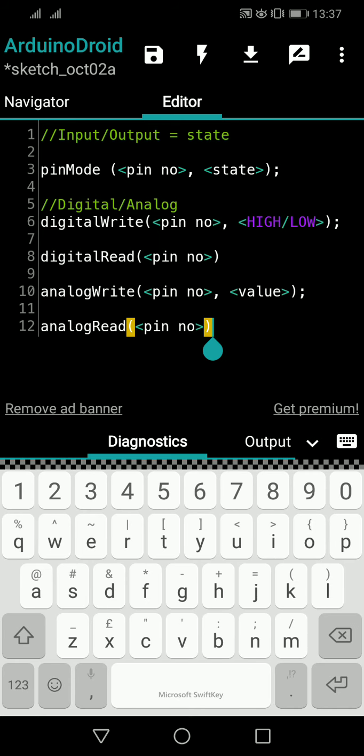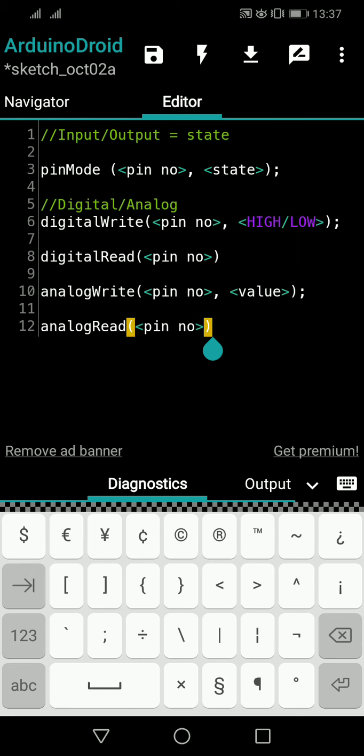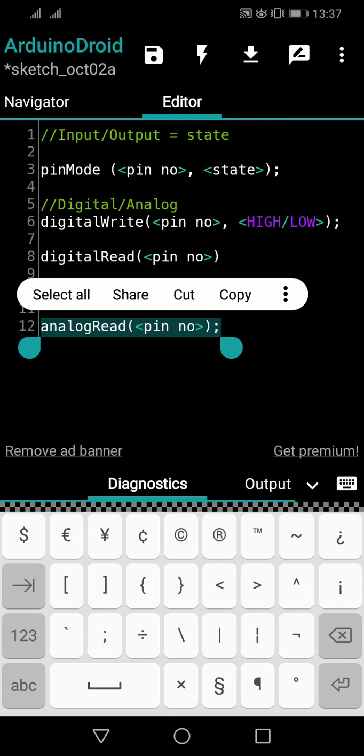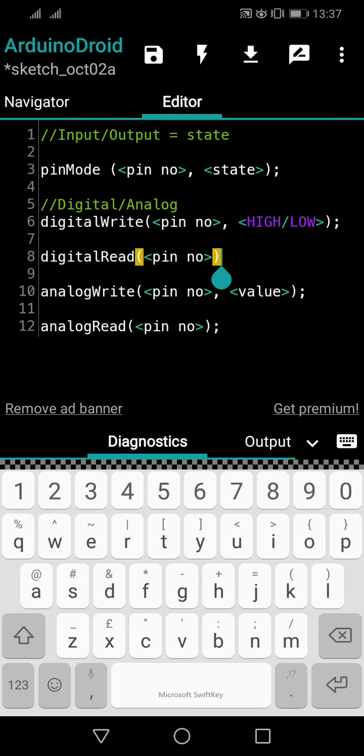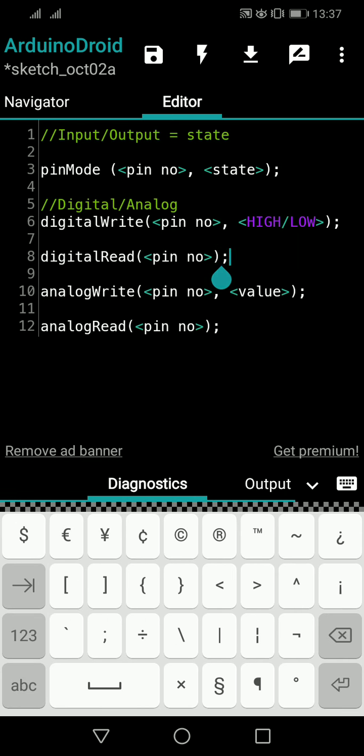Also remember, even when we take the analog input, like the digital input, we have to assign the input value of this function to a particular variable. Don't worry about that now, because when we study analog inputs, we will have a look at that. So please remember, for digital input the keyword is digitalRead, and for analog input the keyword is analogRead, and we pass the pin number, that's enough.